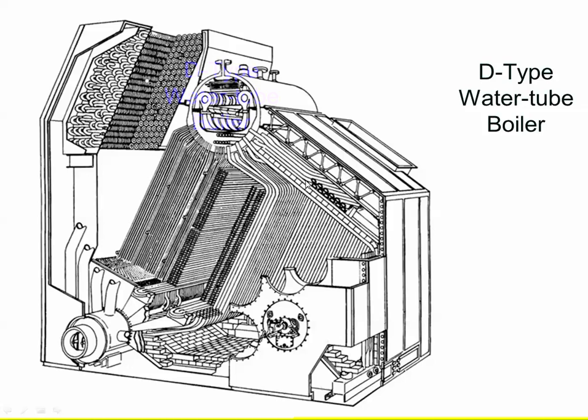Now we're going to be lighting off a boiler from cold. Again, this is a very large boiler. It has to be brought up slowly, specifically from dead cold. So what we're going to do is light off with a minimal, absolute minimal fire. It takes 4 hours to bring this boiler up to full capacity. You're not to see any pressure, anything coming out the air cock for at least an hour. And if you did, you shut the burner off, wait for the hour to have transpired, and then light it back off again.